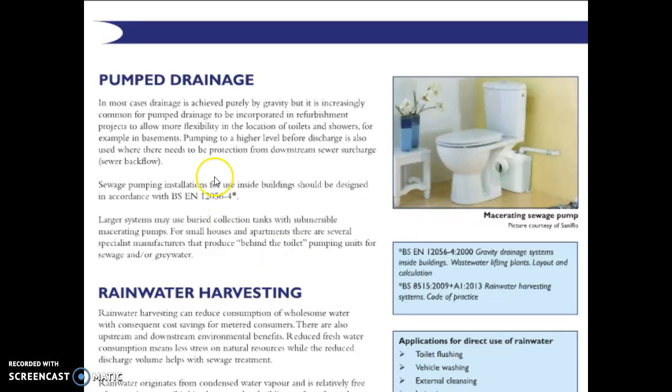In certain applications, and typically in domestic areas, we can utilize what we call pump drainage, and this is where the effluent is captured in this box. We have a macerator in there, which basically breaks it all up into liquid form and then pumps it in a smaller pipe, and instead of falling at a gradient, it can actually take it vertically upwards.